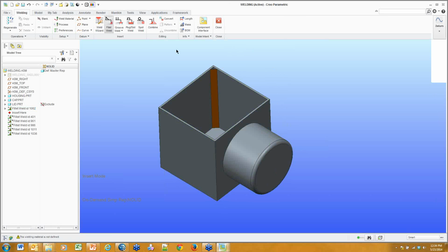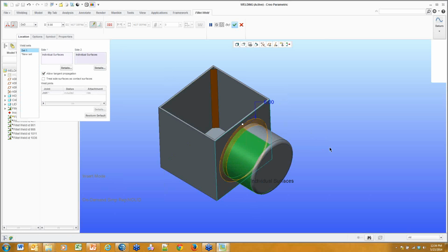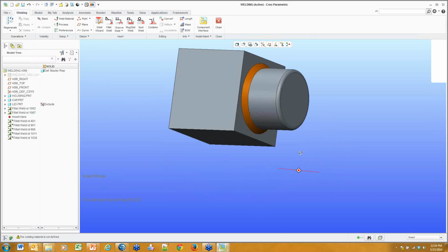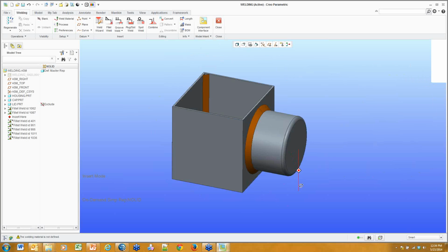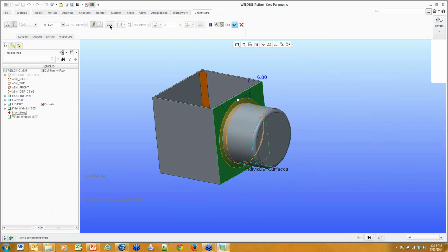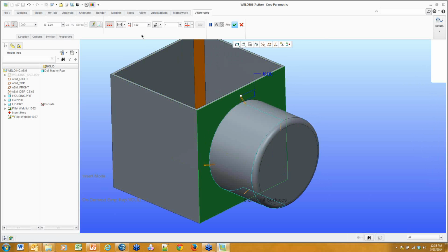But I also want to go back to the fillet weld, and we have this option right here. Let's click on, actually before we do that, I'm going to pick this face and this face. Okay, it's giving me a fillet weld around the entire face. And that's nice and all. Let's see if we can actually edit that a little bit. Let me go back to that fillet weld, edit the definition, and click on this icon here. This icon will allow us to actually split the weld.